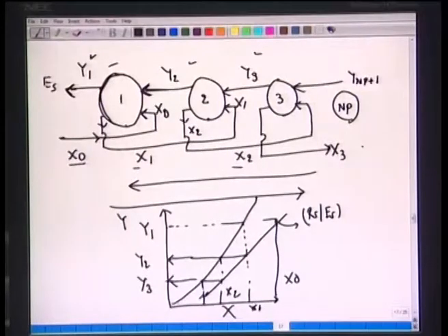Now, it is also possible to treat this as co-current, since two streams are entering concurrently, we have x0 and y2. So, we have x0 and this y2 here, and since it is co-current, we can draw the curve like this with the slope of minus Rs over Es. See, we have the same stage like this. Now, it enters here, we can draw another stage, stage 2, and we can have a stage 3.